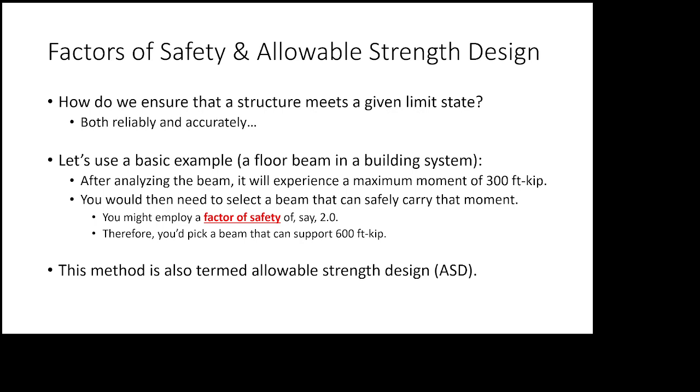Now, let me say this. What you are talking about is 100% something that we have to account for in structural engineering. We do it differently, though. We do not do it through the use of factors of safety. We just assess different limit states.